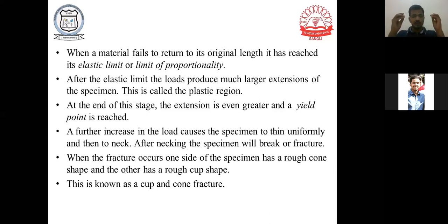Now, even if you release the load on that specimen, it will not regain its original shape. That means after the elastic limit, whatever changes take place in that specimen will be permanent. The specimen's shape and dimensions are changed because we have entered the plastic deformation region.